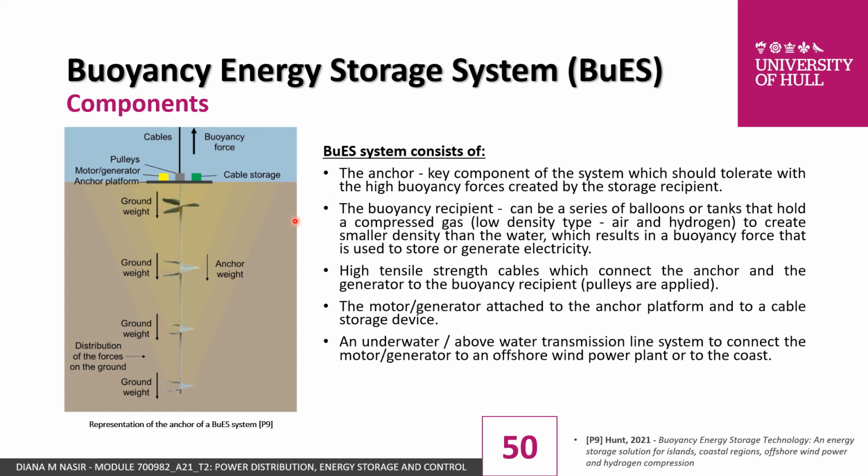The main one should be the anchor, which will be connected to a motor and high tensile strand cables, where a pulley system will be applied. The anchor should be able to tolerate the high buoyancy force created by the storage recipient. Then we also need a buoyancy recipient, where the inner medium should be a compressed gas. Usually it's a low density type such as air or hydrogen, and should have a lower density than the water to create the buoyancy force.